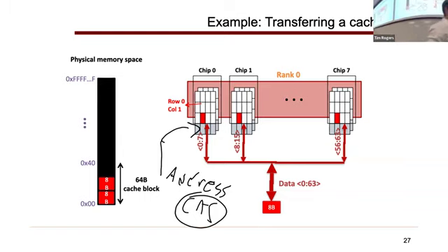So in typical DRAM memory systems, if you're going to read from one row, you have to do RAS, CAS, CAS, CAS, CAS. If you wanted to light up different rows in different banks, you'd have to send separate commands, and that would take extra cycles. But what would usually happen is that this first RAS takes some time. Opening up that row takes some time.